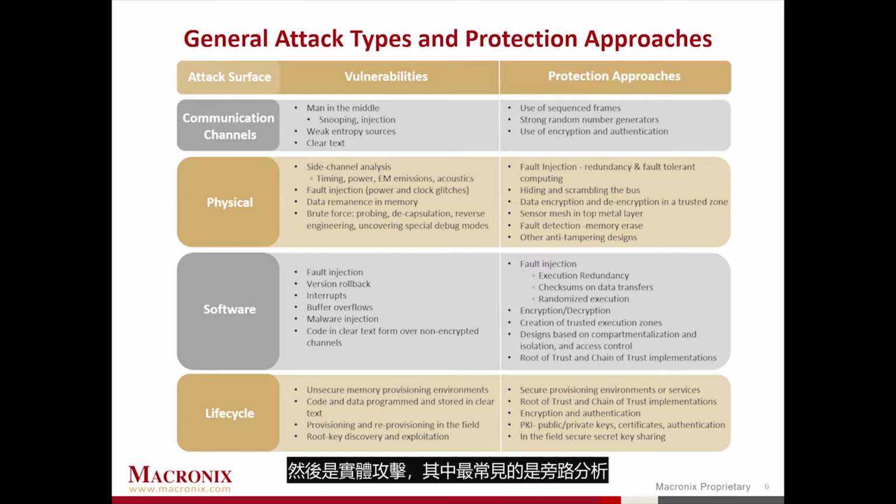Then there are physical attacks, and some of the more common ones are side channel analysis. Basically studying the physical emissions of the design or timing, and trying to learn more about the system, or inserting faults on the clock or the power lines to glitch it and to see how it behaves, or turning the device off and looking at data that's left in memory, or brute force, just probing or decapsulating, or trying to uncover special debug modes to learn more about it.